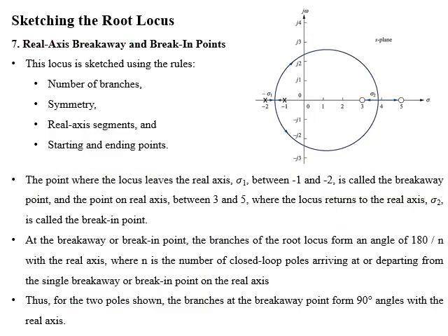Dear students, now we will sketch the root locus for the system given in the figure. This system has two real poles and two real zeros. Poles are located at -1 and -2, whereas zeros are located at +3 and +5. We will find the number of branches and will maintain the symmetry of the root locus.